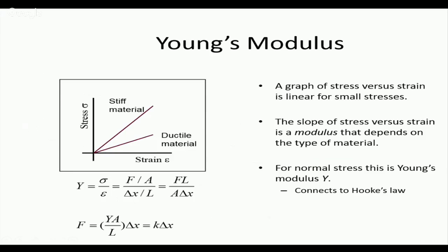We have Young's modulus. As you all probably know, every material has certain material properties, and one of the major ones is the Young's modulus, which is defined as the elastic modulus. And when we apply loads or strain, we can measure the stresses. Load versus deflection curves can be obtained, and we can calculate the stresses. So from the stress strain curve, in the elastic zone, we can obtain the elastic modulus.